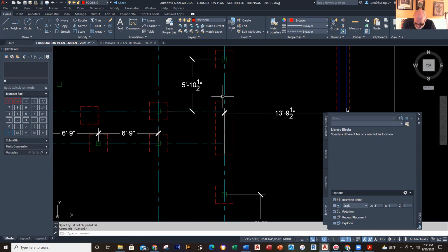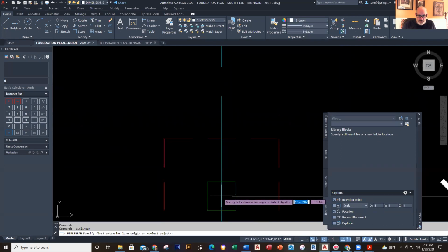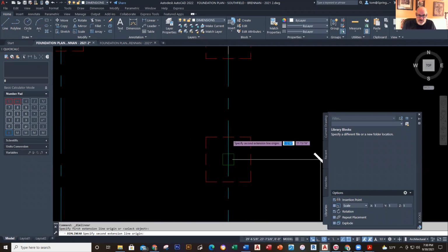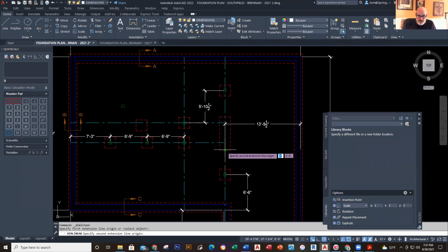Like that. Okay, then I want to at the 5 feet. So let me measure that, then put a dimension there, make sure it's right. We're here, dimensions, linear. Okay, so that's not right. So why is that not right? Oh, it's okay. It went down. It needs to go up 6 inches. Okay, so move that up 6 inches. So move that up 6. All right.